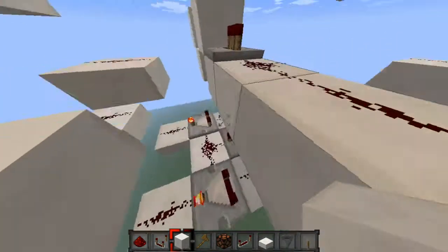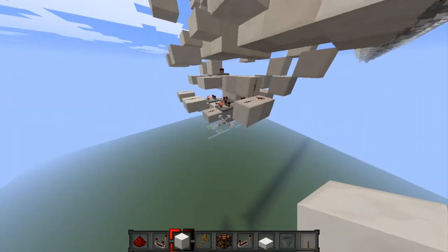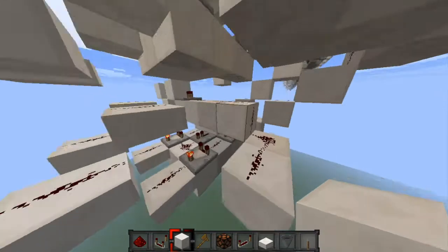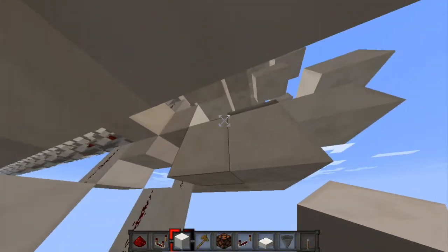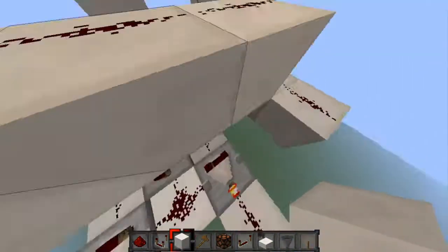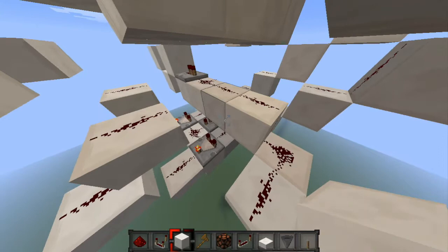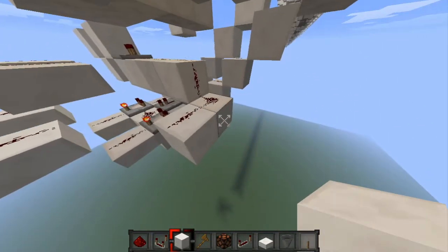Anyway, so let's talk about what exactly it is we're doing right now. So right now we're making the decoder for the 2 least significant bits for this thing right here, which is the 2 most significant bits shifted down to the 2 least significant bits. So this is shift 3 times to the right. So that means that, let's see,